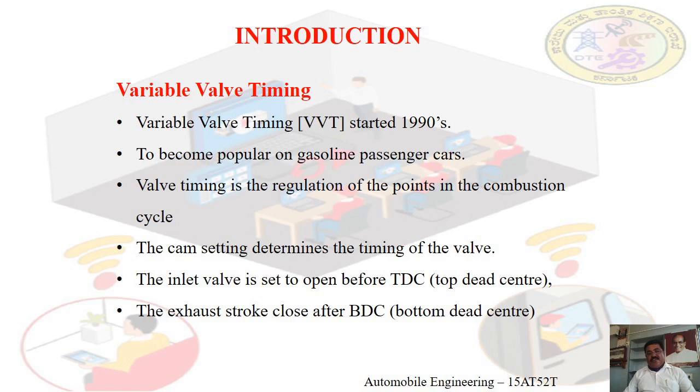Valve timing is the regulation of the points in the combustion cycle. The cam setting determines the timing of the valve. The inlet valve is set to open before top dead center, and the exhaust stroke closes after bottom dead center.